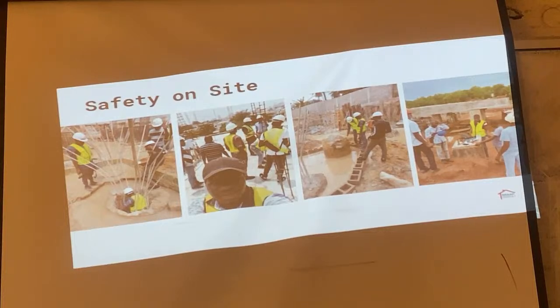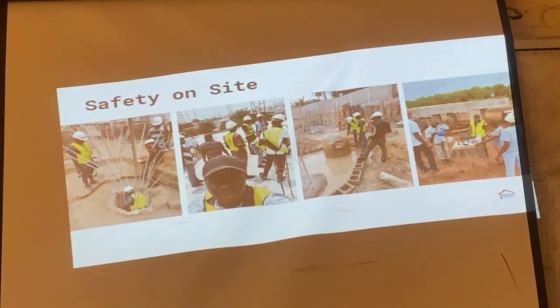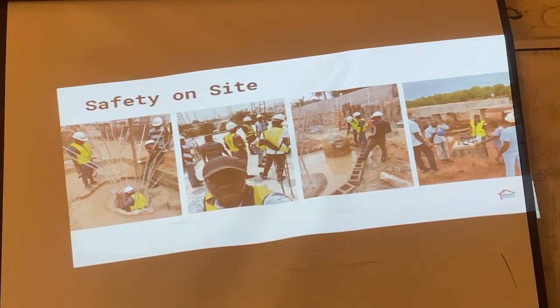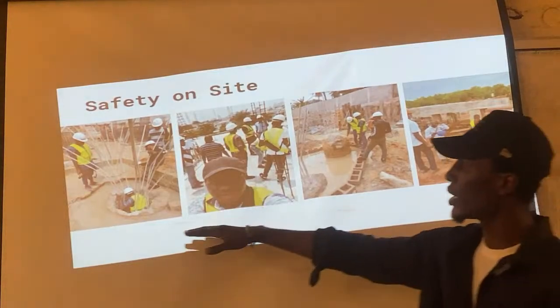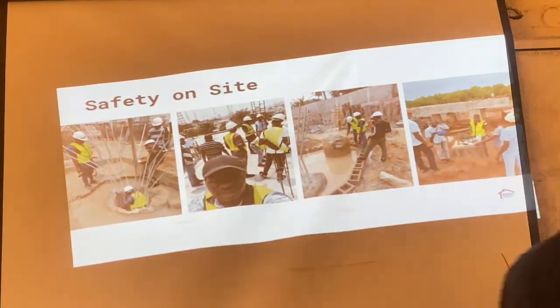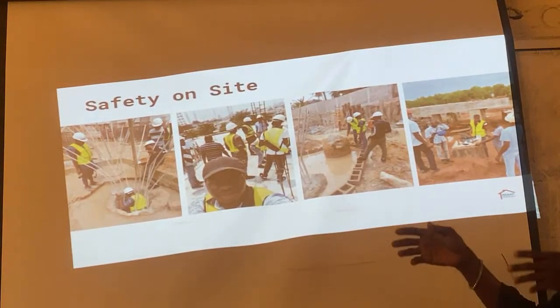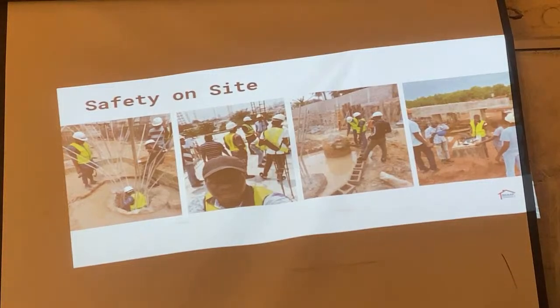Sorry, I thought you got me. All right, so let me make it like this. You know about pile load test. So what kind of pile load test do we have? We have static and we have dynamic. But are we putting any load on this? So that means it's not the pile load test. This is a pile integrity test. We are carrying out the pile integrity test using a UPV machine, using the Pundit machine.